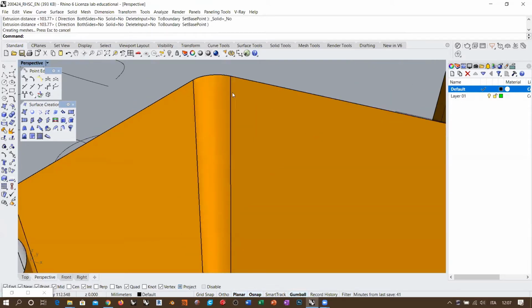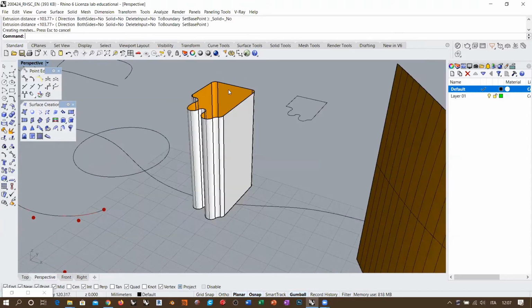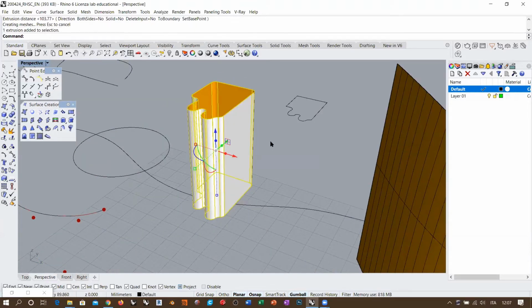each fillet becomes a surface. So we still have a polysurface. So we created a more complex result, even if we were smoothing or rounding. Well, this is not smoothing, actually. This is rounding the corners. So if we round the corners, we create a discontinuous connection between the sides, because the fillet is a constant radius curve.